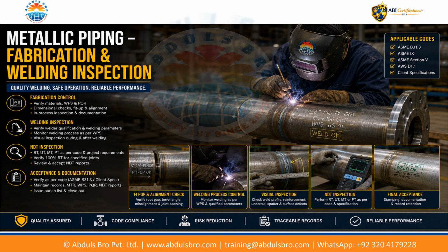Let's have a look at metallic piping fabrication and welding inspection. Metallic piping inspection requires systematic control of fit-up, welding, dimensional compliance and examination. Before welding, QA/QC verifies material identification, joint preparation, alignment, and applicable tolerances. Welding is performed by qualified personnel in accordance with approved procedures, with weld identification and traceability maintained.